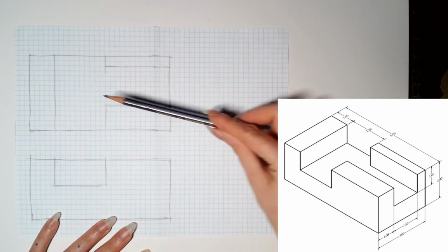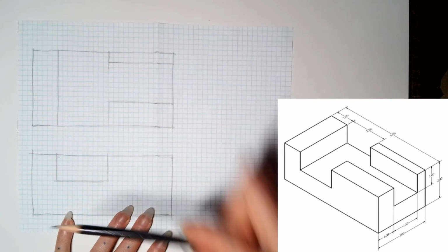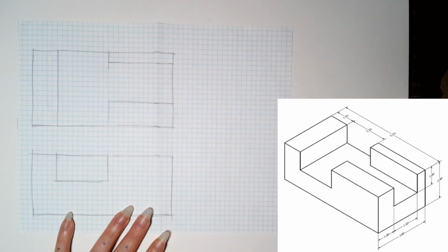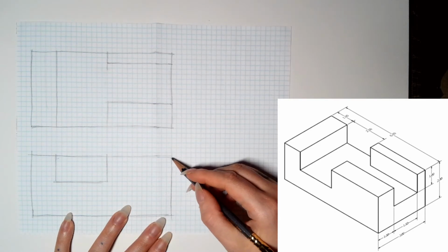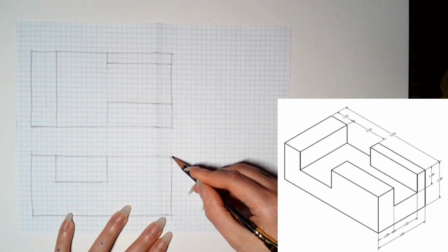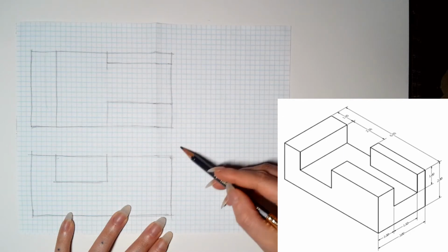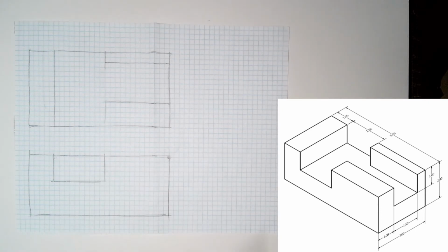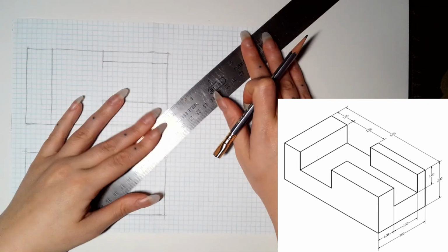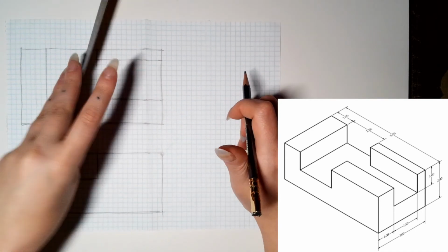But just to show how this is almost like two little rivers that are meeting each other, but then there's still that back face there. So in my side view, if I wanted to do the miter line technique, I would be projecting it this time right from the corner of the object where the two of these are meeting. And I would just project my 45-degree line. I could take a ruler and just put it across all the diagonals.